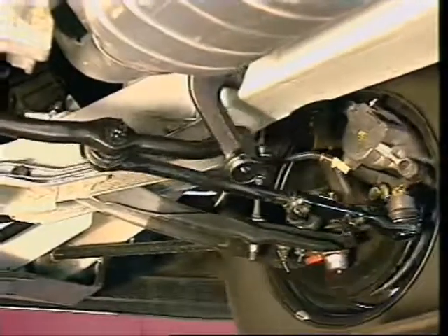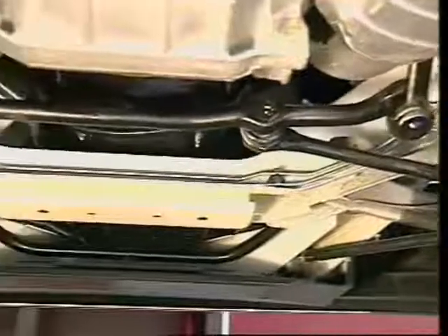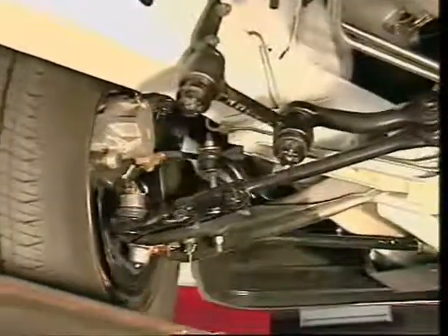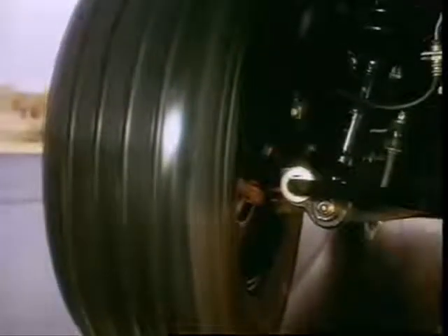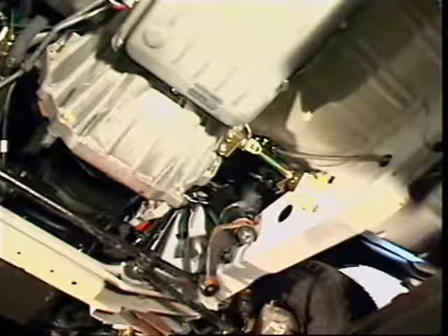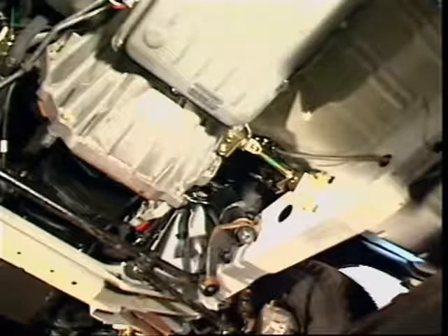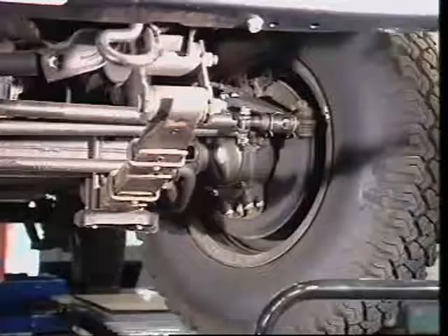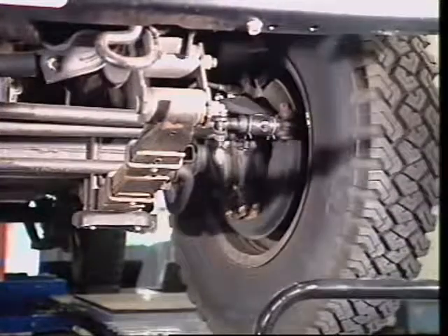The steering linkage is a combination of rods and arms that transmit the movement of the steering gear to the front wheels. It must transmit this movement to the front wheels while still allowing for any up and down movement they may make while the vehicle is in motion. The type of steering mechanism and the number of linkages depends on the type of steering box, its location, and the type of suspension on the vehicle.